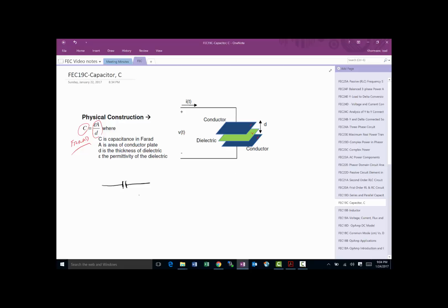But for our discussion here, we're going to assume we have a standard ceramic or polymer-based capacitor. And in those cases, it's a passive device. So if the current i(t) is flowing in this direction, the voltage that would be created is going to be plus minus, much like a resistor, much like an inductor. And then that would be the voltage across it.